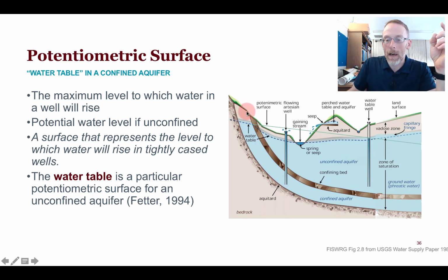Water can rain on this narrow band of surface where we have permeable bedrock and go straight down to the water table. Once it gets into that rock, though, it's trapped there. It's trapped in this unit because it's got a confining bed to the right and above, and a confining bed to the left and below. And remember, the other word for a confining bed is an aquitard. And then as we get underground, if you come straight down from the surface here, this portion of the aquifer, the confined portion of the aquifer, is isolated from the Earth's surface by the confining bed.